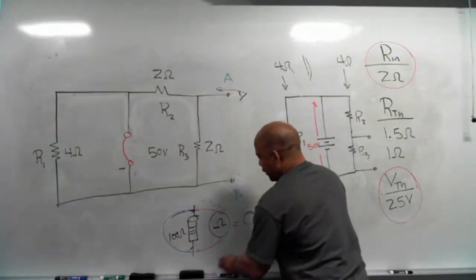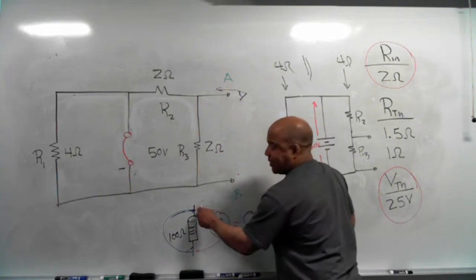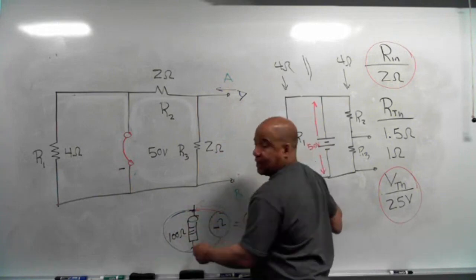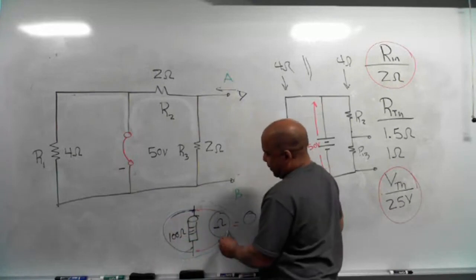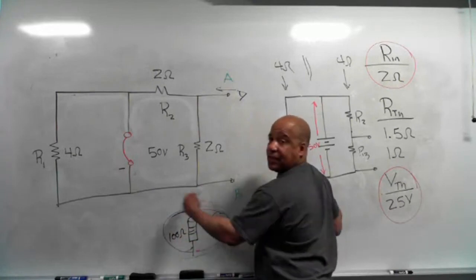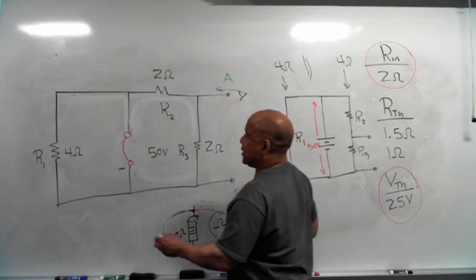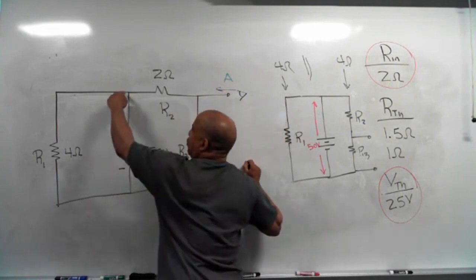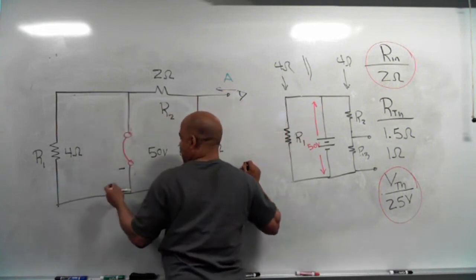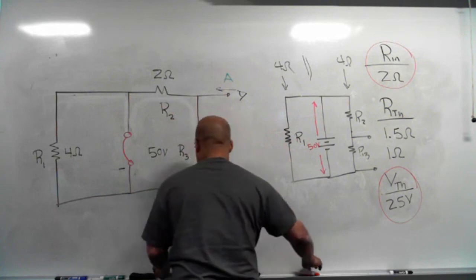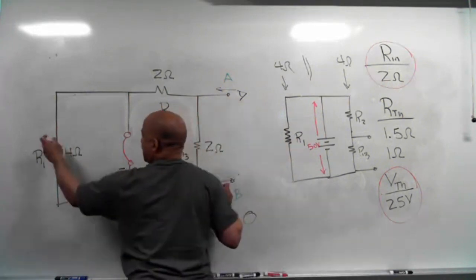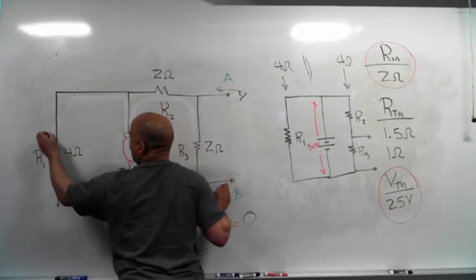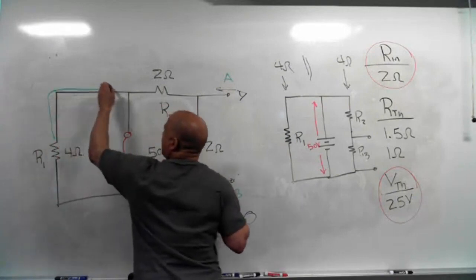When that ohm meter sends the current out, current takes the path of least resistance. The short doesn't have any resistance, so current's going to bypass the resistor and go back to the ohm meter. It's going to think there's nothing out there. So anytime you have a resistor connected to itself through a wire, the resistor is shorted out, it's like it's not there. If you look carefully at this, this resistor is connected to itself through this part right here.